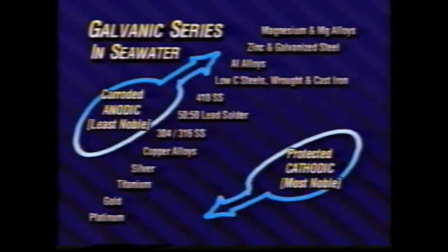Some alloys, most notably the stainless steels, can be either passive or active. Therefore, they may occupy two places in the galvanic series, a relatively noble position for the passive state and a less noble position for the active state. The passive protective barrier that makes such metals much less susceptible to further reaction is fairly stable over a wide range of oxidizing power. However, destruction of the film restores them to the active state. Thus, certain acids can be very harmful to an otherwise corrosion-resistant passive alloy.